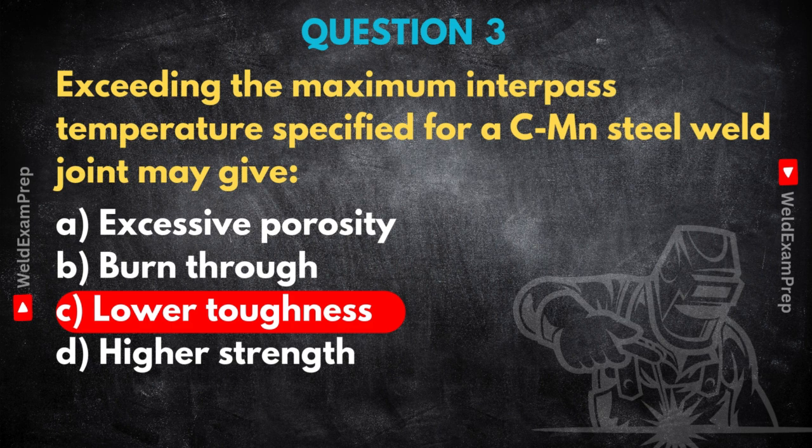You mentioned grain coarsening. Can you paint a picture of that? What does it mean microscopically, and why do bigger grains make it less tough? Yeah, think of the steel's structure like a brick wall. Each grain is a brick. The boundary between them is the mortar. Finer grains mean lots of small bricks, lots of mortar lines. These boundaries actually help stop cracks from running straight through. If the grains get coarse, you have fewer bigger bricks. A crack finds it easier to travel a longer distance without being stopped or deflected. That makes the material less able to absorb energy before it breaks.